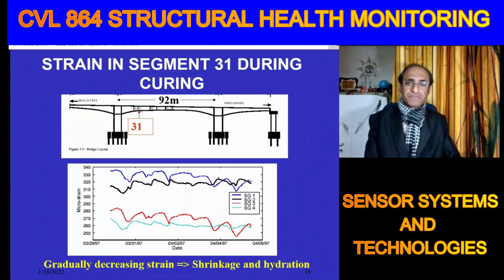There is no lack of technology for that. If you are doing it in the lab, you do a direct connection. For example, in our lab, we are doing a direct connection from the sensor to our data logger. But at the site, these days cloud is used. They use a small local data logger that collects the data from the adjoining sensors, and then through wireless technology, the data is transferred to the cloud.